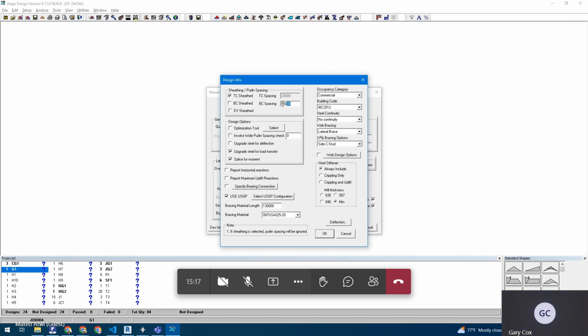So if you enter 20/16ths, it will convert that to 1.25 inches automatically. The next two numbers to the right of that are reserved for inches, and you always have to use the leading zeros in those. You can't leave them off. So this would be 6 foot, 11 inches, and 15/16. Correct. For inches and sixteenths, you have to use the leading zero for the numbers.